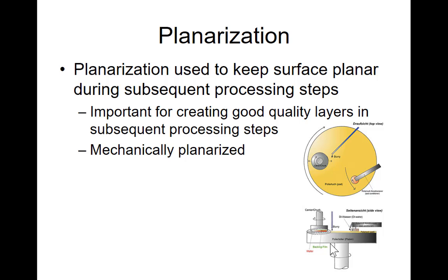So this CVD is a step. CMP is a step that you also use again and again. So after you put some material on it, it's non-smooth, then you do a CMP. You can do CMP to polish it, and then you are ready to do the next step.